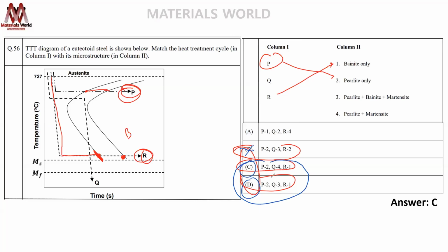And here is the important part. Do you understand this transformation? If you understand, you see here I am in the austenitic region. I start my transformation above the nose, and it's exactly 50%. It's exactly the intermediate, central line. This is the start line, this is the finish line, this is the 50% line. As you can see here, it's touching the 50% line.